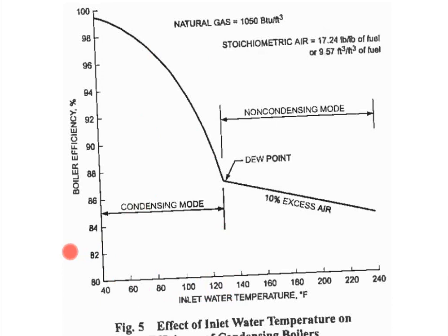So a radiant system, if you think about it, I can't send 180 degrees to the floor, right? Because a 180-degree floor is going to be really hot for people to stand on and extremely uncomfortable. So usually I'm limited to like 110, 115, maybe 120 supply, which means I've got low hundreds for my return water. So even on my normal radiant system, I'm already making this 86% boiler look like a 92, 93% efficient boiler. And then as I reset the water temperature lower, it gets even more efficient. So a radiant system is going to make your boiler operate more efficiently than it's rated, just for the simple fact that I'm going to have a cooler entering water, which is causing the condensation to happen earlier.